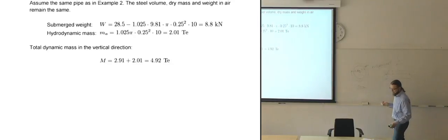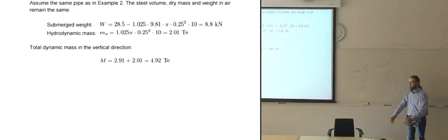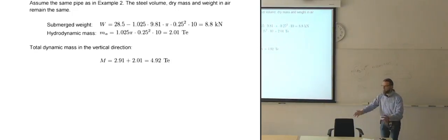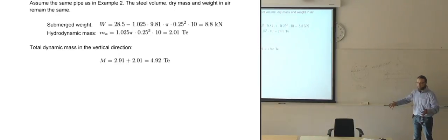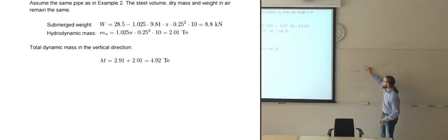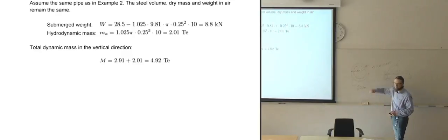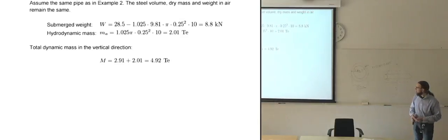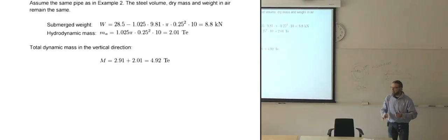But of course, if you're filling it with air and you're lowering it down to 500 meters, 1,000 meters, 3,000 meters, you need to have the strength in place in the steel, or else the steel is just going to collapse. So if you have too thin walls on the pipe, it's going to basically just be compressed like a soda can if you fill it up with air. So it's not ideal having something filled with air when you're putting it down.